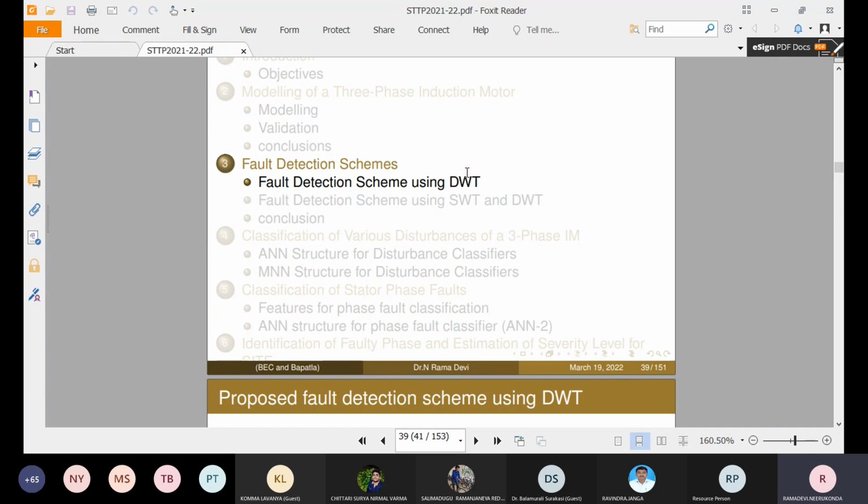So that's why we call the wavelet transform a multi-resolution analysis transformation. When the signal is analyzed in the time domain as continuous, the wavelet transform is called the continuous wavelet transform. When the signal is a decomposed signal, then the signal is discrete, because we apply the wavelet to that discrete signal. We call it the discrete wavelet transform.